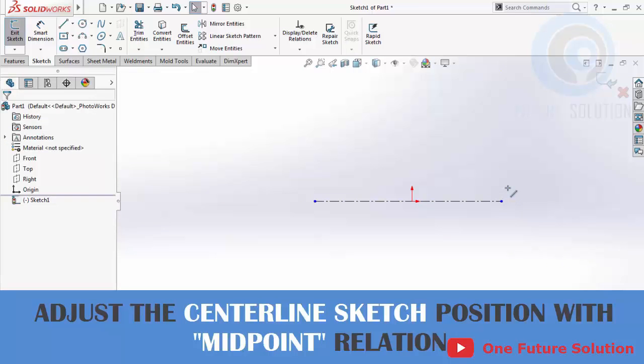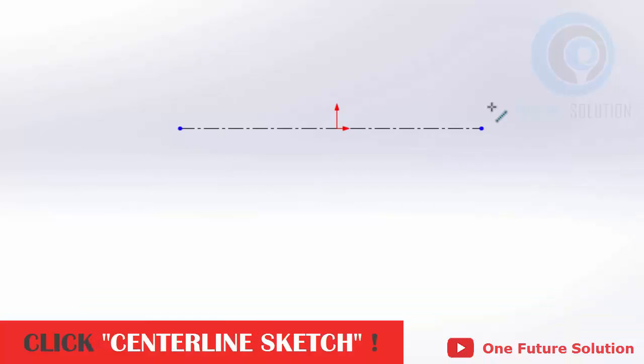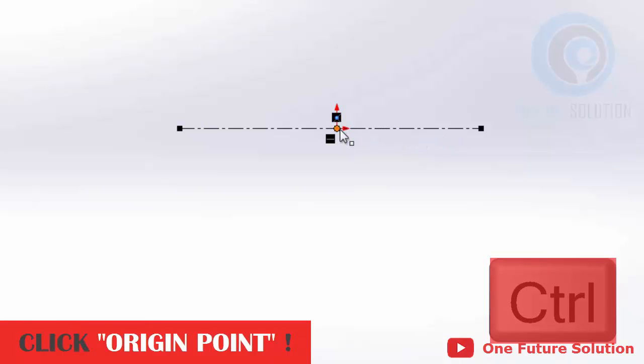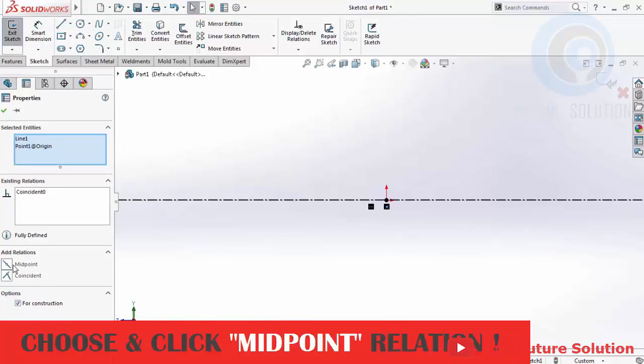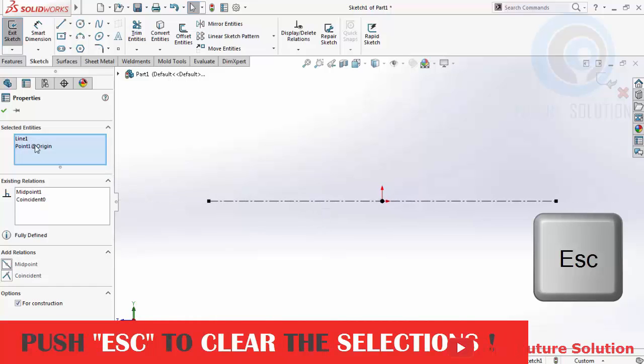Now, adjust the Centerline sketch position to the middle of the origin point using the midpoint relation. Click the Centerline sketch. Push and hold the Ctrl button to select more than one item. Click the origin point. After we select these two items, choose and click the midpoint relation. Okay, push the Escape button to clear the selection.